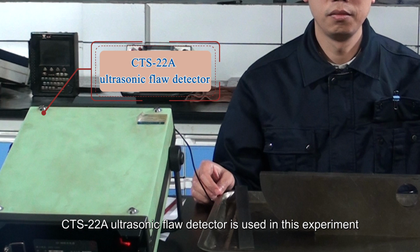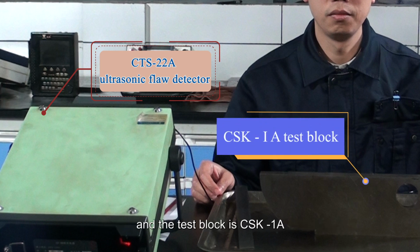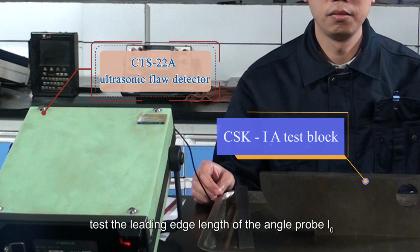A CTS-22A ultrasonic flaw detector is used in this experiment, and the test block is CSK-1A. First, test the leading edge length of the angle probe, l0.